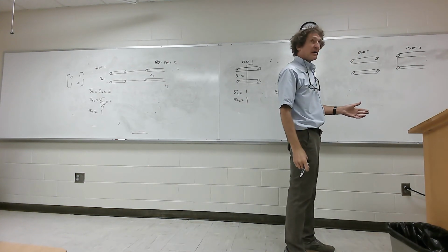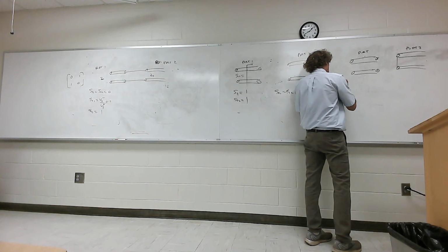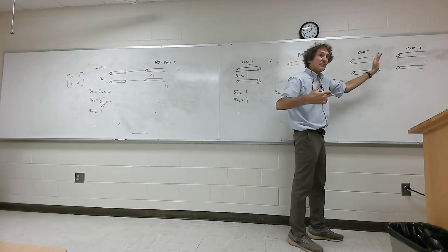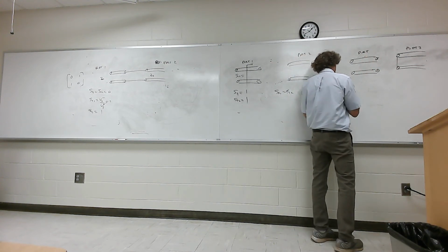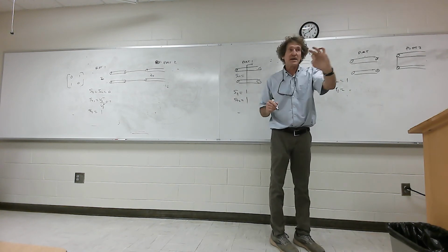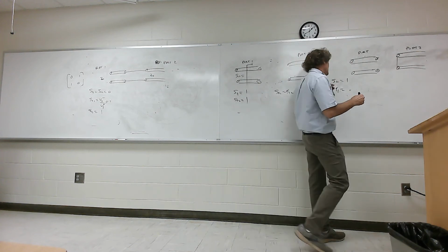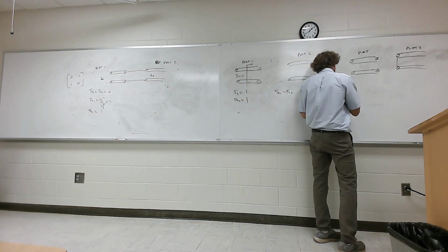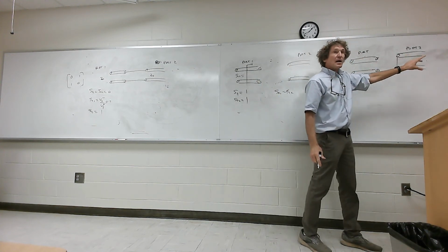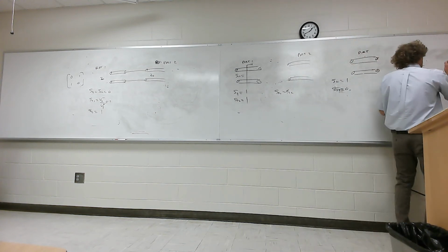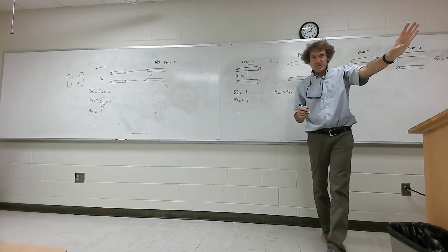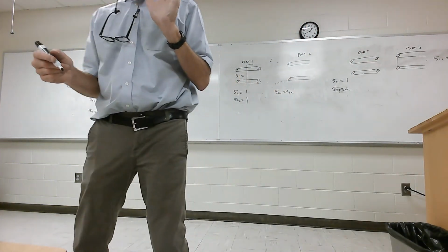Now take one look. What is S11? That's an open circuit. Infinity minus something finite over infinity plus some is going to be 1, right? Now, what's the transmission coefficient there? 0. Nothing gets over there, right? Absolutely nothing. S21 is 0. Just leave it like that. There is no connection. No way any signal from here can get over there. Now, what's the reflection coefficient over here? S22 is going to be minus 1. Exactly. That's a short circuit. So I go from 0 minus Z naught over 0 plus Z naught, which is minus 1.